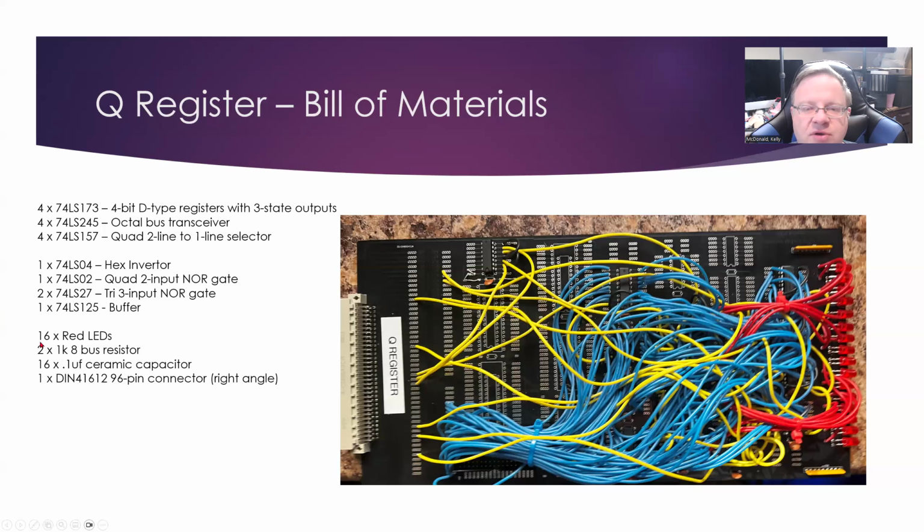Associated components, we've got our 16 red LEDs to show the contents of the Q register, along with their current resistors so that we don't sink too much current. And then we've got our 0.1 microfarad ceramic capacitors for each chip, just to, again, make sure its power supply is nice and happy. And then we've got our 96-pin connector that we use to connect to our backplane.